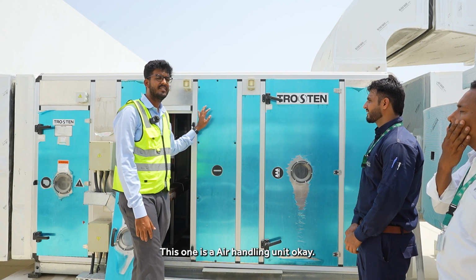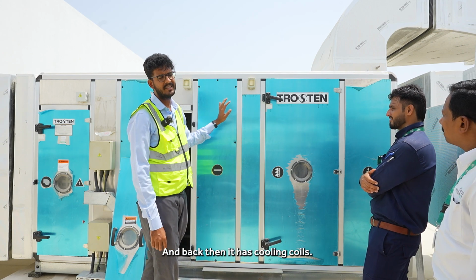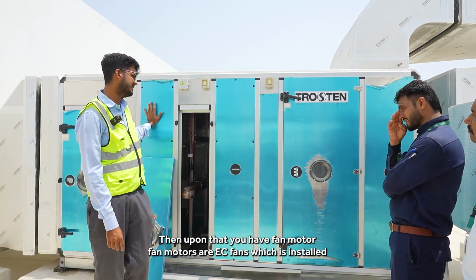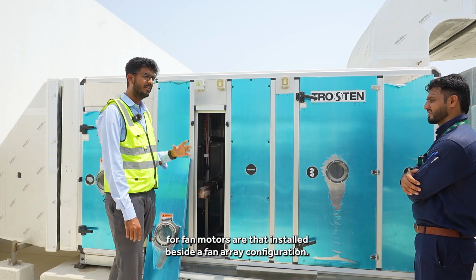This one is the air handling unit. It has two-stage filters, pre and back. Then it has a cooling coil. Then it has a UV lamp in it. Then upon that you have the fan motors. The fan motors are EC fans. Four fan motors were installed, in a fan array configuration.